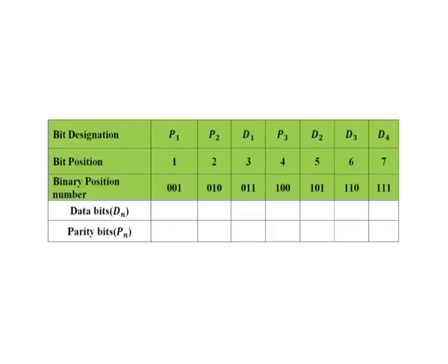Finally, we must assign a 1 or 0 value to each parity bit. Since each parity bit provides a check on certain other bits in the total code, we must know the value of these others in order to assign the parity bit value. To find the bit values, first number each bit position in binary, that is, write the binary number for each decimal position number as shown in the second 2 rows of the table.